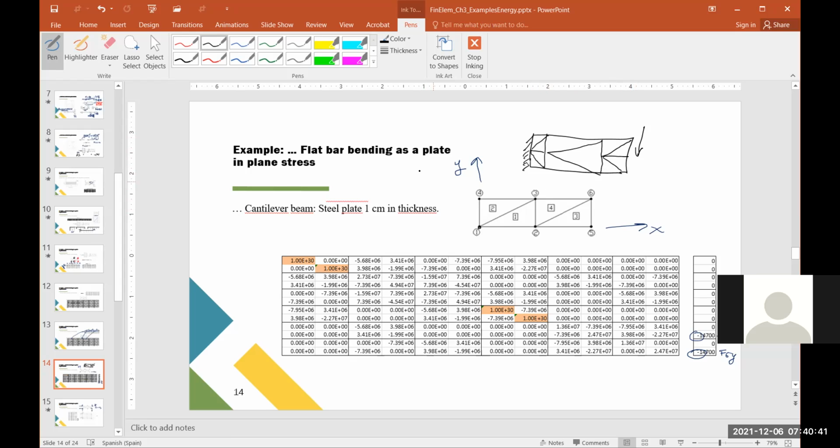And remember that the problem is, let me show here. Let's suppose that this is the correct solution. It includes curvature, right? What we're doing is partitioning this domain in these points with these elements, and then we're trying to approximate with straight lines. So in this area around the foundation and around the place where you apply the force, of course, you expect a larger gradient than in the central area, right? So what we can try to do is include more elements in this area where we have the support. And after this element, you can have more elements in the upper direction. Similarly for this area.